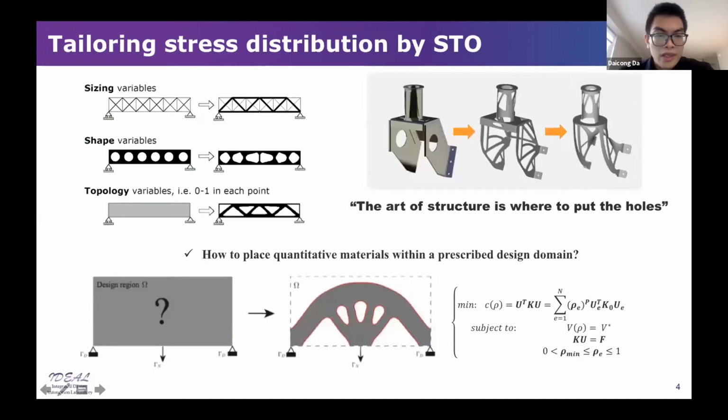So in our study, we will try to combine both the structural topology optimization method and data-driven techniques. Topology optimization is a well-known method right now to tailor the material structure geometries to achieve the best performance, such as here, a very classical compliance or stiffness maximization problem. You can try to minimize the structural compliance subject to a volume constraint.